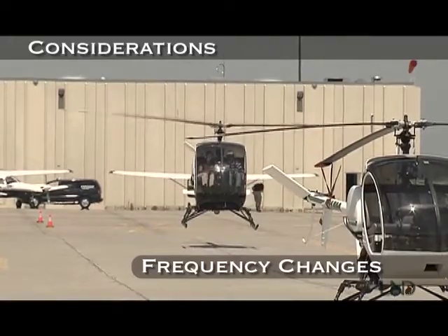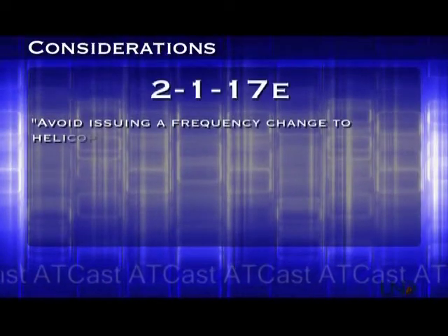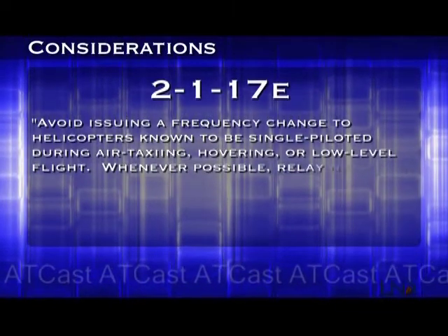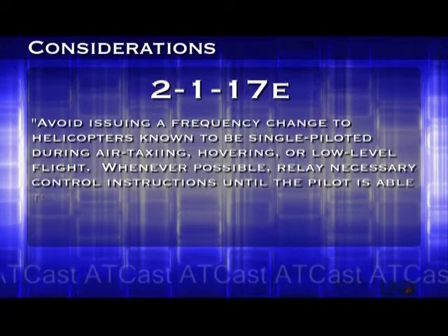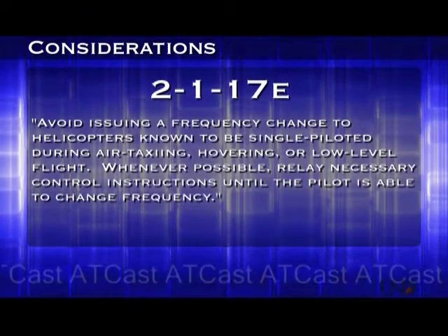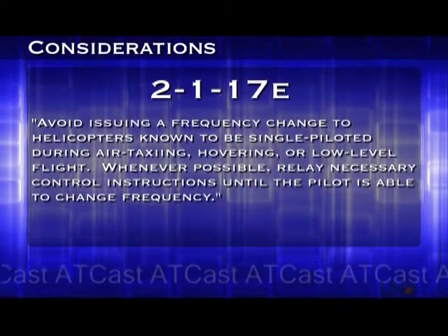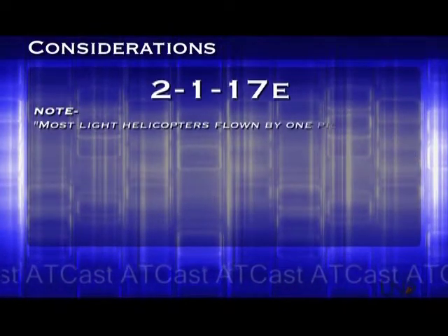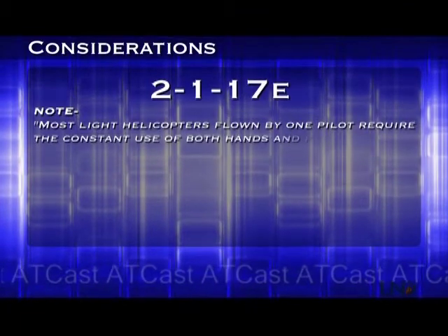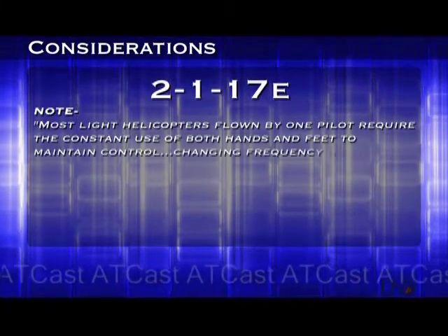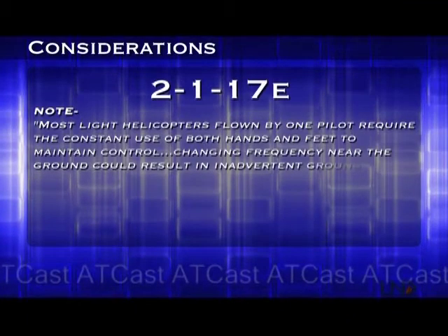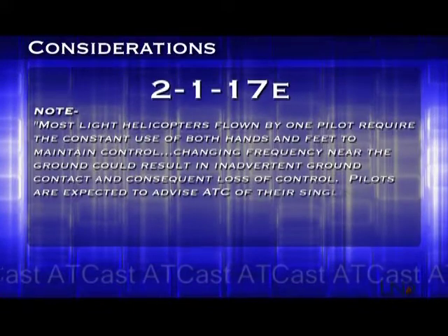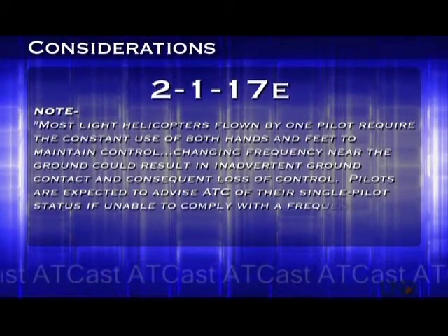The 7110 says, avoid issuing a frequency change to helicopters known to be single-piloted during air taxiing, hovering, or low-level flight. Whenever possible, relay necessary control instructions until the pilot is able to change frequency. The note that follows explains why. Most light helicopters flown by one pilot require the constant use of both hands and feet to maintain control. Changing frequency near the ground could result in inadvertent ground contact and consequent loss of control. Pilots are expected to advise ATC of their single pilot status if unable to comply with the frequency change.